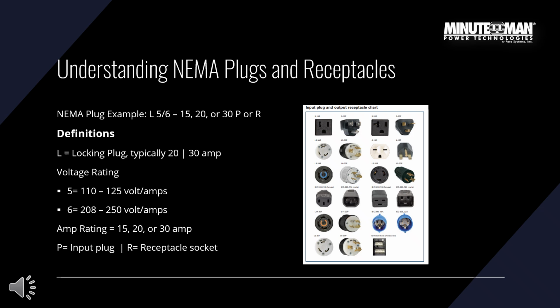Plug and receptacle compatibility. It's important to note NEMA plugs and receptacles must match exactly to connect safely. A 5-20P plug won't fit a 5-15R outlet, and that's by design. We want to prevent overloads or unsafe wiring. Never modify a plug to fit a different receptacle, and always check voltage, amperage, and configuration.